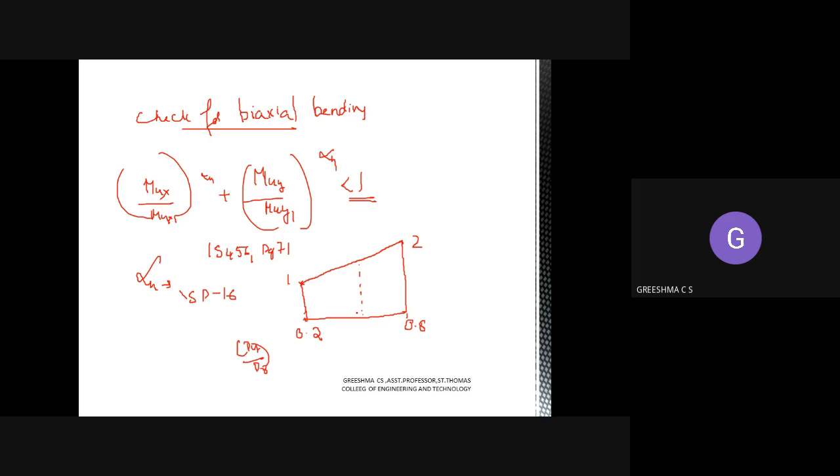Okay, so here the PU by PUZ value you got as 0.396. So approximately we can take it as 0.4. PU divided by PUZ value you got as 0.396, round it and make it 0.4. Find out the alpha n value, how much you are getting. So this you will get as 1.8. Interpolate and find out, you will get it as 1.8.